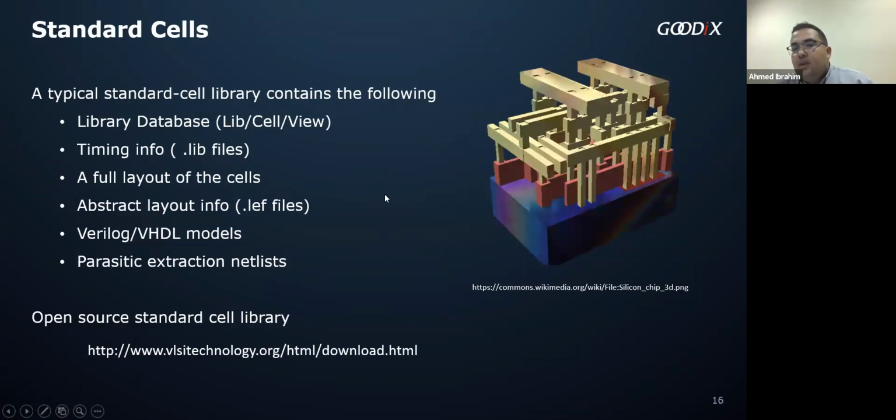Standard cells. Actually, there is a misconception that standard cells are part of the PDK. It's not actually a part of the PDK, because standard cells are like IPs. So maybe a foundry can sometimes produce them, but foundries or third-party design houses can provide different IPs, based on a certain foundry PDK, of course.